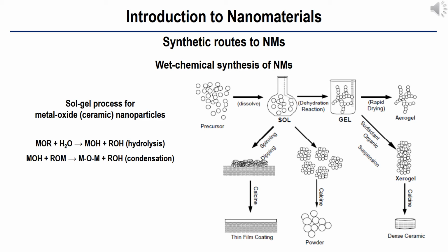5. Dehydration, during which surface-bound M-OH groups are removed, thereby stabilizing the gel against rehydration. This is normally achieved by calcining the monolith at temperatures up to 800 degrees Celsius. 6. Densification and decomposition of the gels at high temperatures, above 800 degrees Celsius. The pores of the gel network are collapsed, and remaining organic species are volatilized.